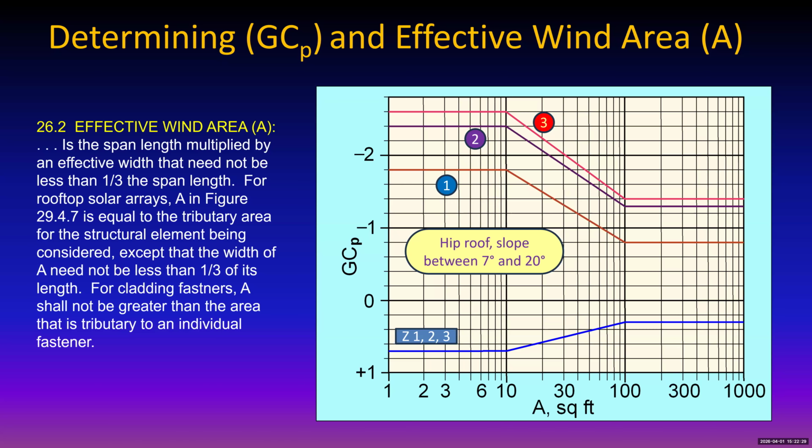so that you can get rid of a few of those mounts. But the manufacturers will say that, well, that's all well and good, but there's still a limit to how far away you can space the mounts underneath the rails, because the rails themselves can bend and be a problem. And if there's a wind that's gusty, you can get some interesting vibration effects.